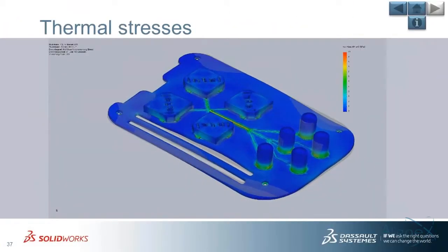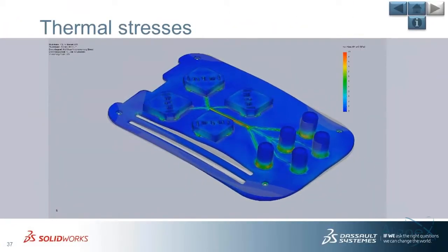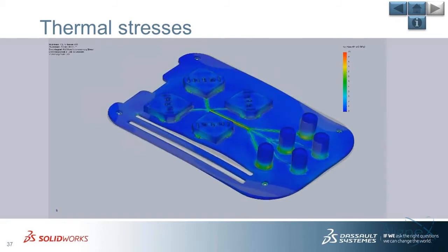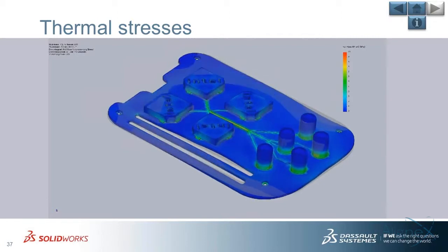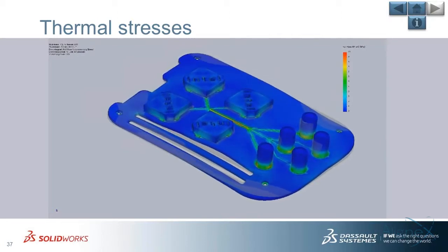And then what we can do, once we solve for a thermal study, once we solve for the temperature distribution, we can also then apply that temperature distribution to a static study where we can look at thermal expansion. So if there's differences in temperatures and where you have different materials and different shapes of structures, you can see that structures will thermally expand in different ways.